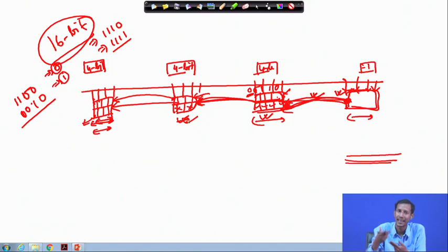So, considering that fact, from the beginning all these blocks run in parallel. That means the computation is done for carry input 0, and also for carry input 1. Now, whenever I get the carry input bit, based on the mux, I will get the sum.